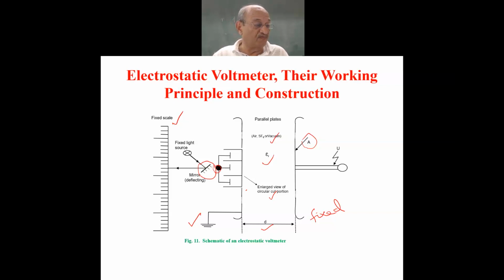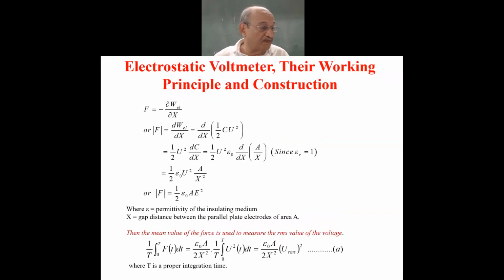So in one way, it's a very simple arrangement, but the only problem is that the size is quite big. For example, we have learned in case of capacitive voltage divider, you need such a big, huge capacitor also for the measurement of peak voltage. So that can be replaced by this. Only constraint here once again is that it cannot measure the peak voltage, it can measure only the RMS value. So this mechanism cannot be used for the measurement of impulse voltages.